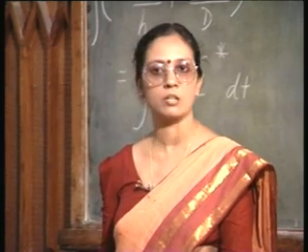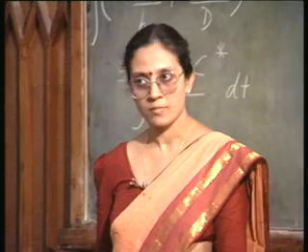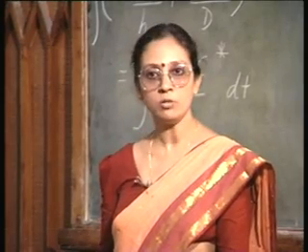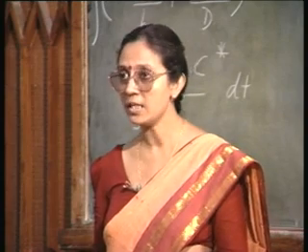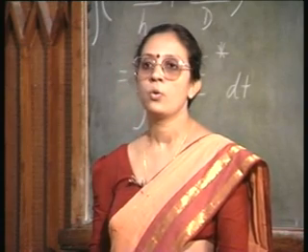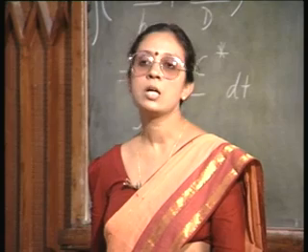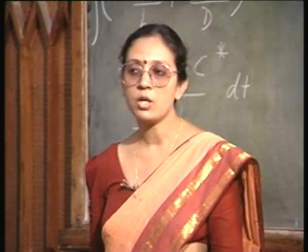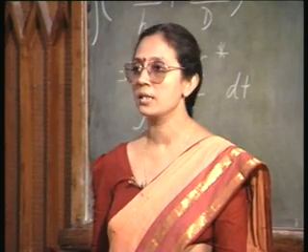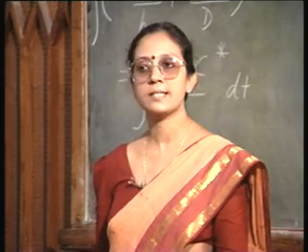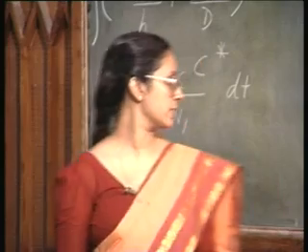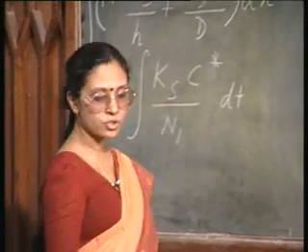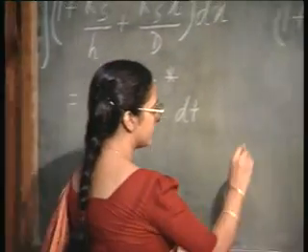That is the most general case, right? That initial thickness could be 0, could also be not 0. So, in order to maintain generality, let us say that when we started the oxidation, the initial oxide present on silicon, let us call it X suffix I, that is initial oxide thickness. So, if that is so, then I can say that